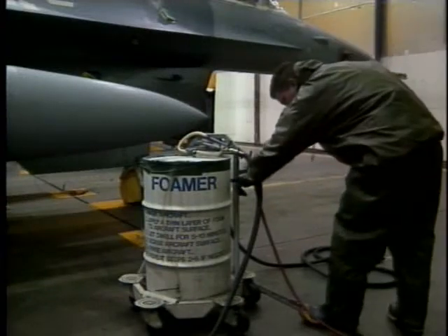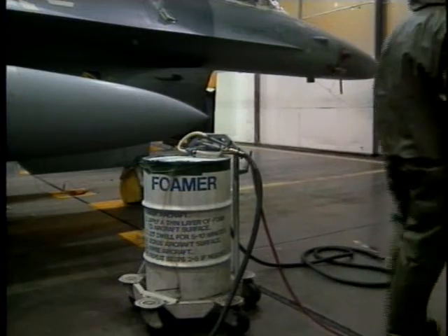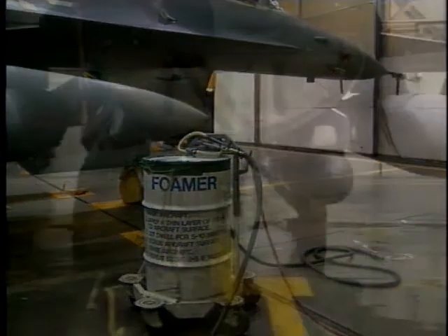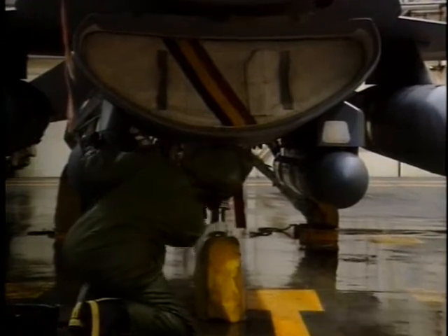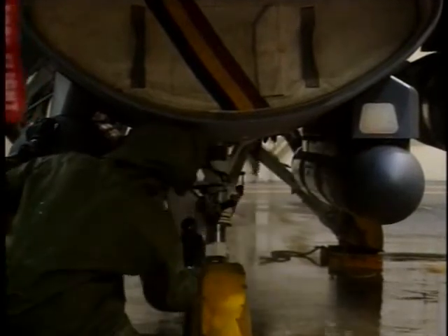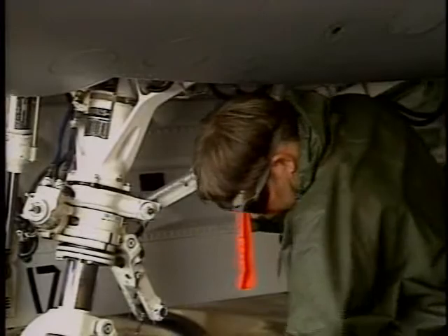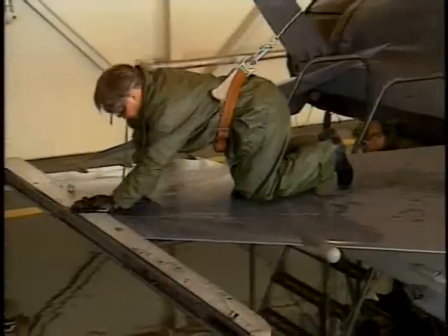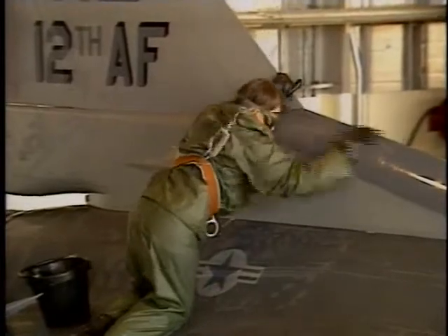Ensure the correct aircraft cleaners are used and the dispenser is set at the proper mixture ratio. Be careful not to direct the aircraft cleaners into areas containing exposed connectors or seal-type bearings. Also, avoid spraying it into areas where there isn't adequate drainage. When you're scrubbing the aircraft, clean the heavily soiled areas thoroughly. Remember, grease and heavy dirt deposits can promote corrosion faster than other areas.